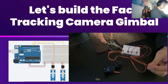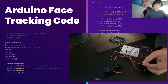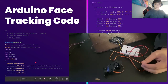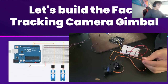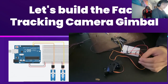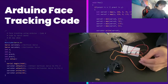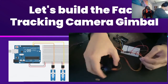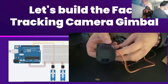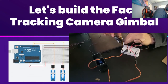For those wires, we're going to be using 5 and 6. I believe 5 is for, let me see, right there, 5 is for the vertical servo, and 6 is for the horizontal servo. But if you have only one servo, then all you're going to be connecting is the horizontal servo, which is going to be connected to servo pin 6. This is my horizontal servo, the one that I connected to here, the bottom one. So from here we're going to go to, I believe it was 5.